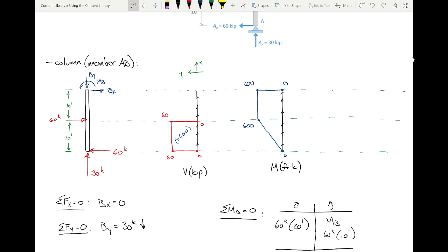It doesn't mean the behavior's wrong or the answer's wrong. It just flips your answers. Okay, I just want you to recognize that. Here's the thing. If I have a beam that's right in front of me, I can draw the shear diagram. Now imagine the beam was here and I then decide to look at the beam this way. The shear diagram actually flips. Doesn't mean it's wrong. You're just changing the direction in which you plot it. Does that make sense? Any questions on that?